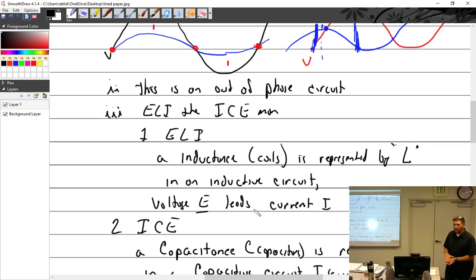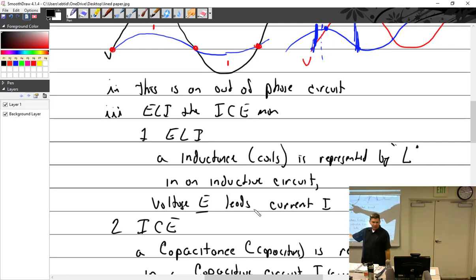So, all right, then the voltage starts to build up because it took time for the voltage. But the electrons were free to run because they had absolutely no resistance whatsoever, and they start filling up that plate. And then here comes the voltage builds up. By the time the voltage builds up and starts to fall back off and go the other way, all the electrons are going, dead end, the other plate's the way to go. So they go running by and fill up the other plate, and then the voltage gets to the bottom, and then it turns around, starts going the other way. Well, now the electrons already filled up the other plate.